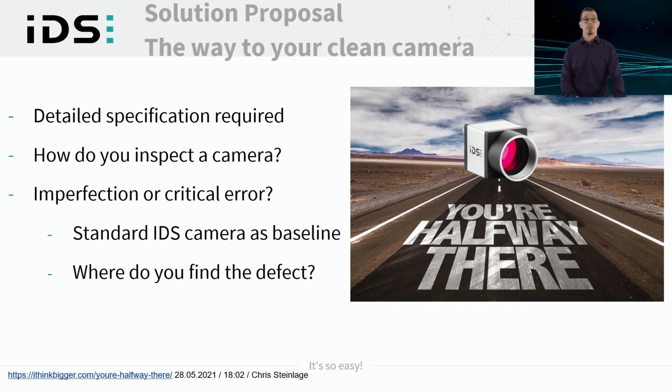So, in summary, it can be said that a detailed requirement analysis based on a few questions can clarify a lot in the run-up to a project in order to avoid surprises or problems later on. A clear, detailed specification is half the job. What kind of application does the customer have? A transmitted light application or a glass inspection? What kind of lighting does the client use? A parallel, diffuse light, orientated light? What kind of lens is being used? What camera is the client using and what settings are used for the camera?